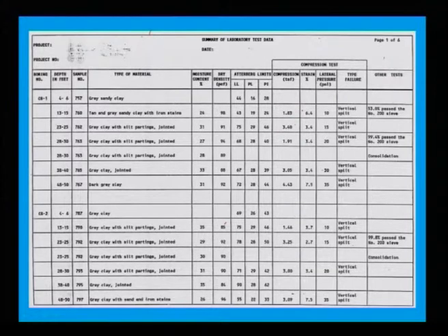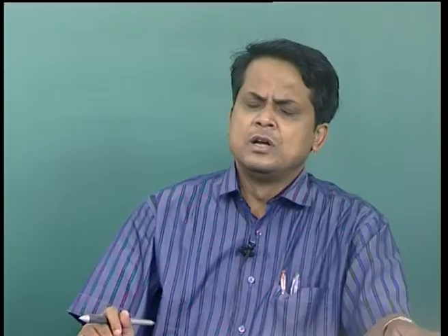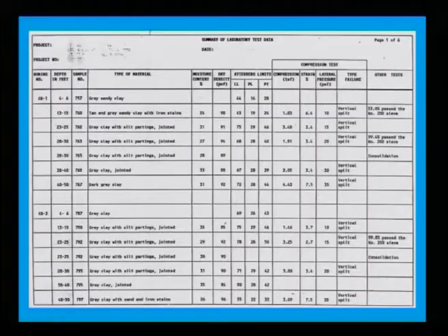Then also you give lateral earth pressure. Lateral earth pressure means K0, the lateral earth pressure at rest. From where will you get K0? As I said earlier, from your dilatometer or pressuremeter, you can find out your K0. This value you provide. Now, the type of failure, what kind of failure you are getting from this?